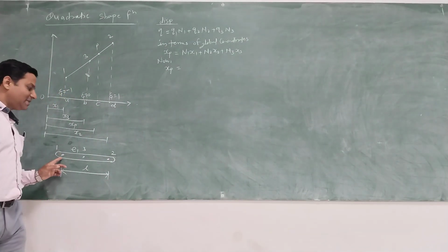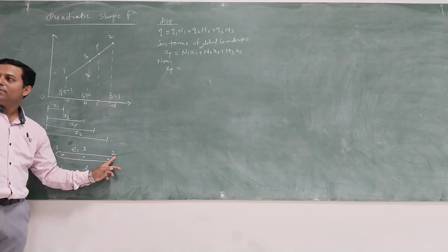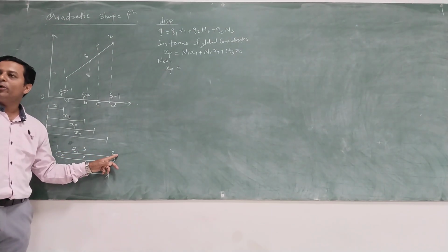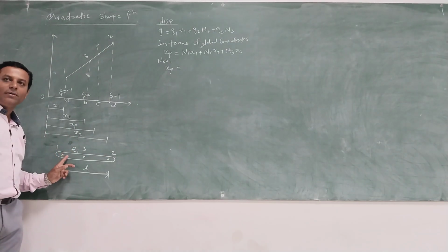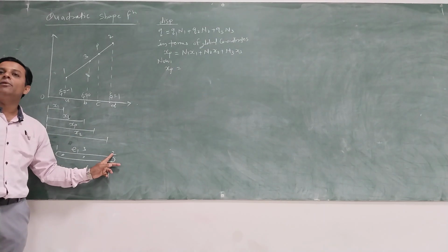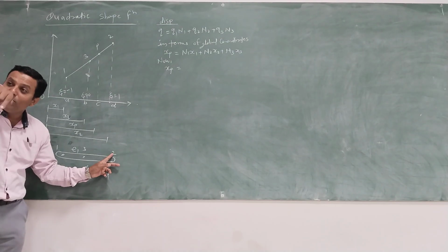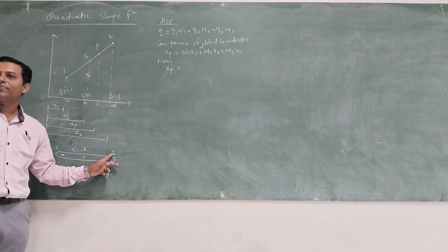See, this is your material bar, and I am going to convert this bar into a 1D problem. So I am going to draw one line. When I draw one line, it will become one element, and for that element I am going to select two nodes, 1, 2. When you select two nodes, it will become the linear shape function, and when you add one more node to that element, then it will become the quadratic shape function.